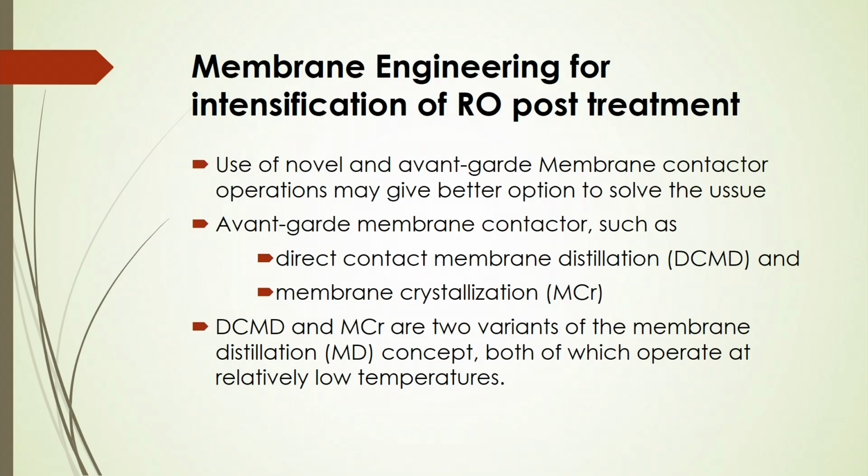Now, if you are considering membrane engineering for the intensification of reverse osmosis post treatment, you know that membrane contactor operations may give better options to solve this issue. In that case, avant-garde membrane contactors such as direct contact membrane distillation and membrane crystallization are the two important aspects of membrane process intensification to have a solution to the brine disposal of the desalination of seawater.